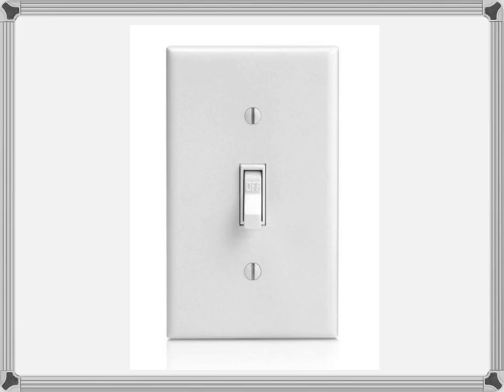When you switch the switch, the signal goes from 0 volts to, with a light switch, 120 volts, because it's home power. When you turn that switch on, it's actually going to vary a little bit between 0 and 120. It's going to go 0, 120, 0, 120, 0, 120 until it turns on. That's called bouncing. Switches physically bounce.